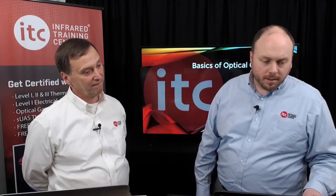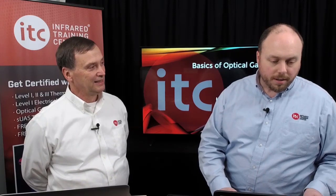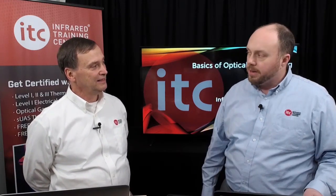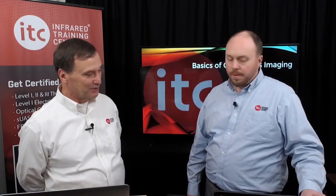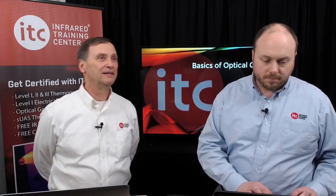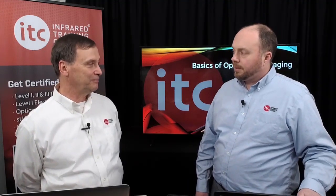Yeah. Okay. Have you tried detecting small leaks? This is small ammonia leaks from Mark with these cameras. How effective was it for leaks that are less than 1 pound per minute? I've never tried to find an ammonia leak. Okay. Yeah, so I have no experience there. And 1 pound per minute, I would say that you probably would have to be in the high sensitivity mode on a tripod to see that.